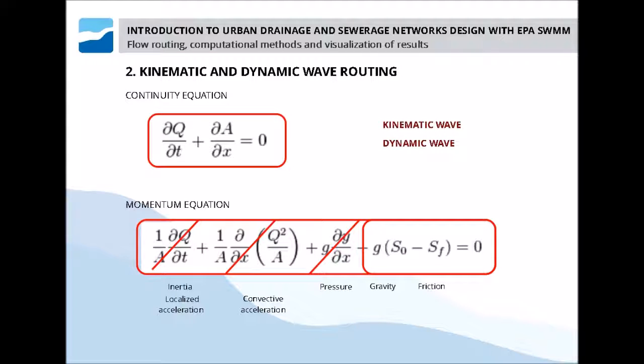In this slide, we can see the aforementioned St. Venant's equations. There is the continuity equation and the momentum equation. In the case of kinematic wave model, only the continuity equation will apply. Whereas for the dynamic wave model, both the continuity and the momentum equations will apply, since the latter includes terms for inertia, acceleration, pressure, gravity, and friction. Inertial terms are those terms that can be ignored or dampened in order to make these equations converge.